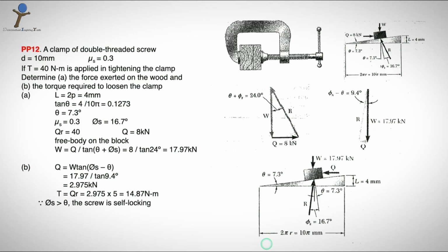So, let us understand an application of a power screw. A very simple application. This is a C clamp. This is the power screw. This part is the nut part which has internal threads, and this part is a movable part. It translates as you rotate this handle.